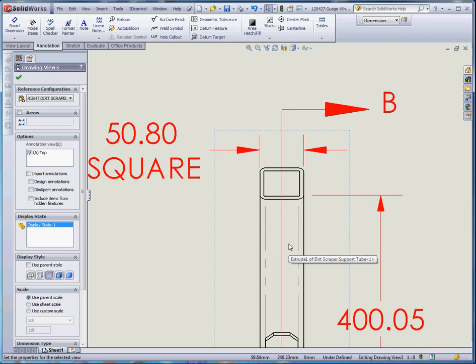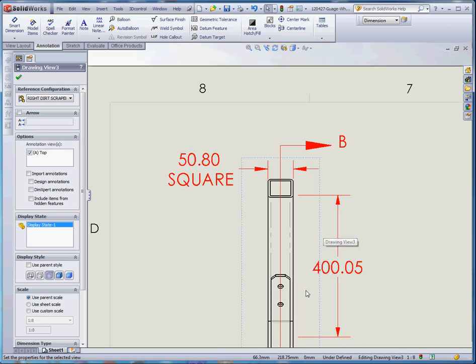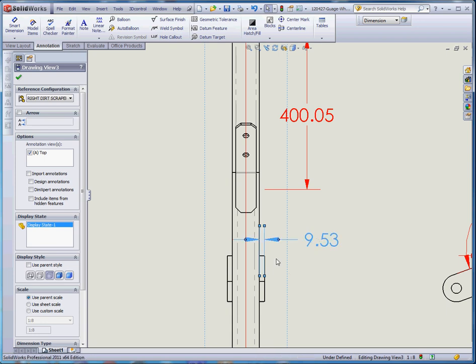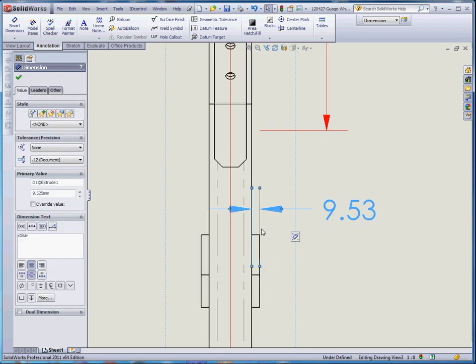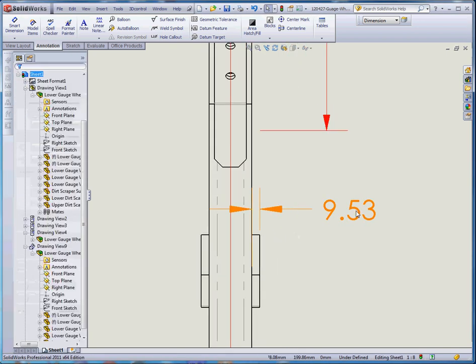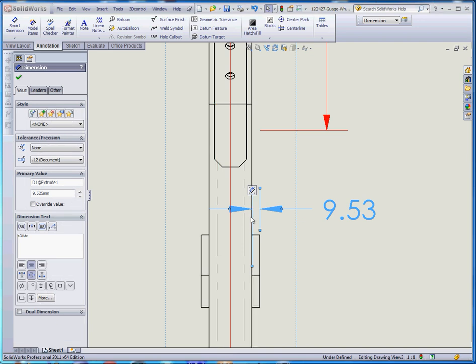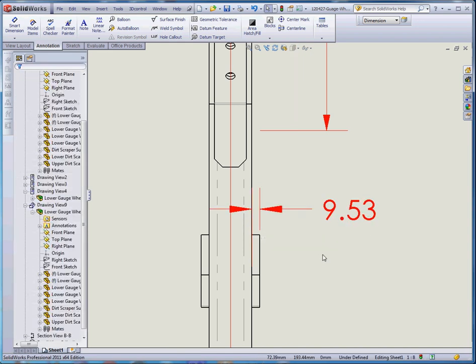The object lines on your page are going to be the darkest lines on the page, the boldest lines, the blackest lines. You don't want anything intersecting with that. So same thing down here. Now this line down here, this other dimension line, is actually embedded, it's part of that, it's collinear with the edge of our object line, and that's probably okay to leave. We can't really leave a gap there.